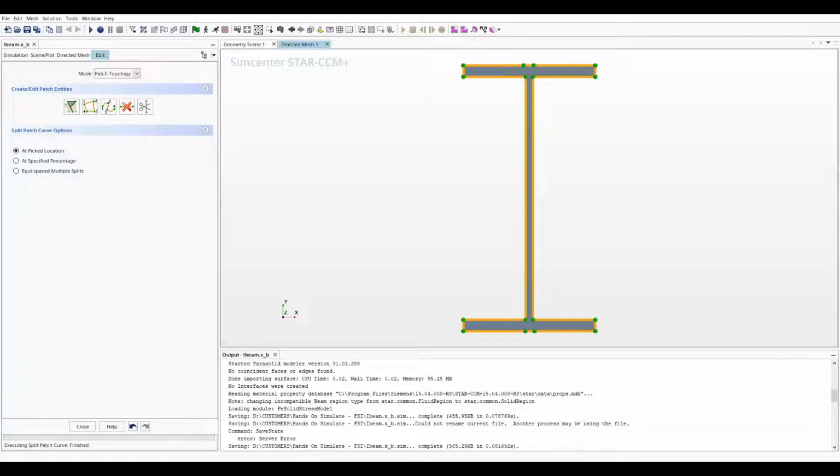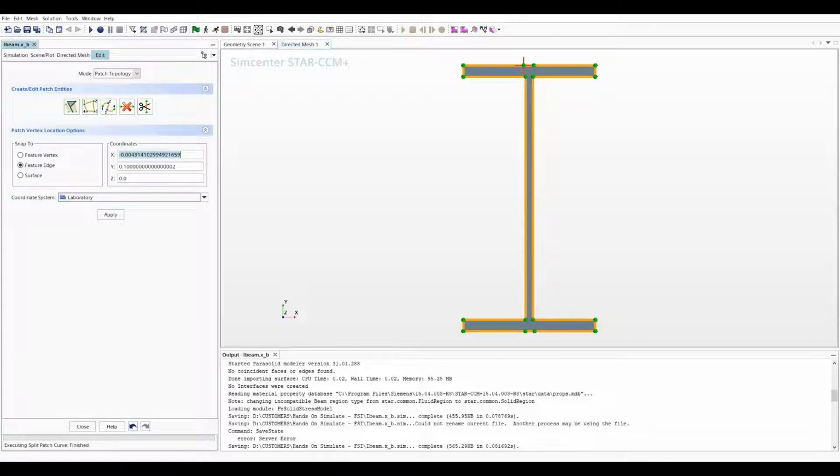Select 4 points right above the existing points on the screen, 2 on the bottom. So maybe it's random points. So let's go ahead and specify the correct coordinates for these points. It is going to be 0.0028 in the negative x direction. I'm going to copy this for ease. The point on the right side is going to be plus 0.0028. Click apply. The bottom one again is negative 0.0028.